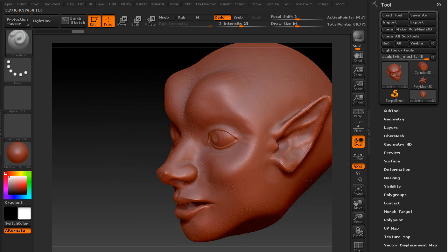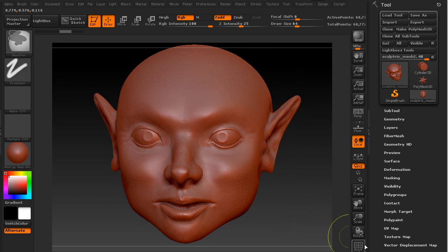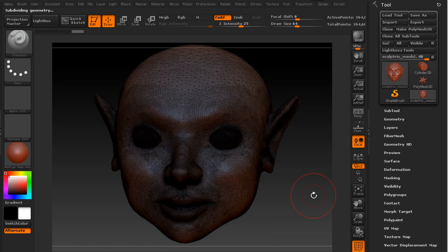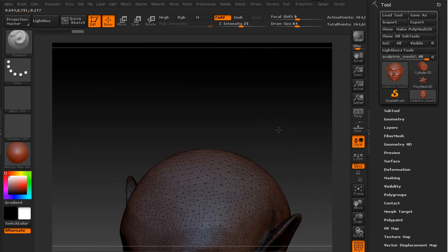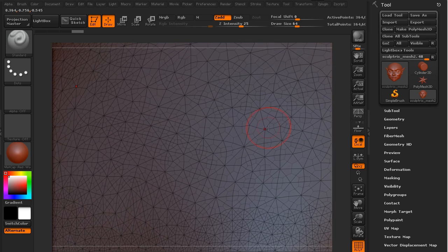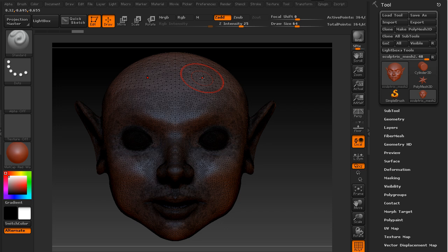Everything works fine for the most part, but if we divide using Control D, you can see what actually happens is that these triangles, and I'll zoom in so you can get a better look, actually get trisected into quads, which can create very unpredictable geometry when it comes to sculpting, because it comes up with some very strange results when we go through polygon flow and those sorts of things. So rather than work with a triangulated model,